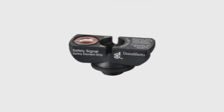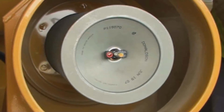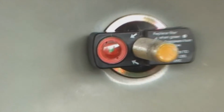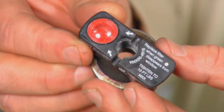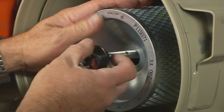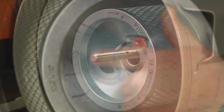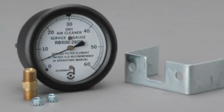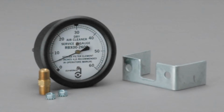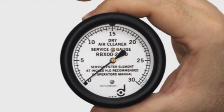The safety signal wing nut indicator replaces the wing nut on the metal end cap of safety filters and constantly monitors air restriction. When service to the safety filter is required, it shows red. The safety signal requires no special fittings or adapters and is designed to last through multiple primary filter changeouts. The service gauge for instrument panel continuously reads restriction when the engine is in operation. It installs conveniently on the instrument panel or almost anywhere.